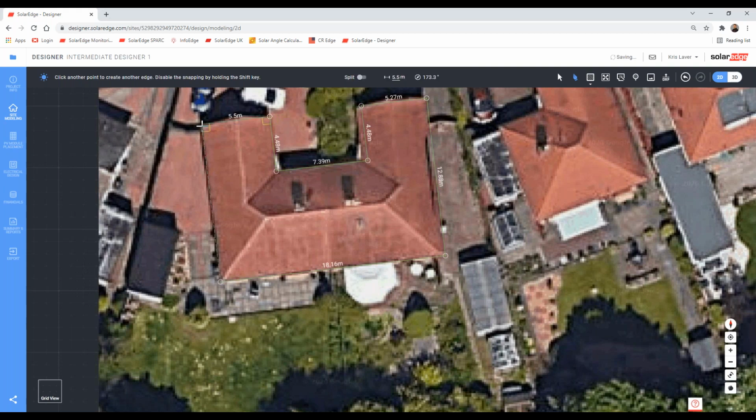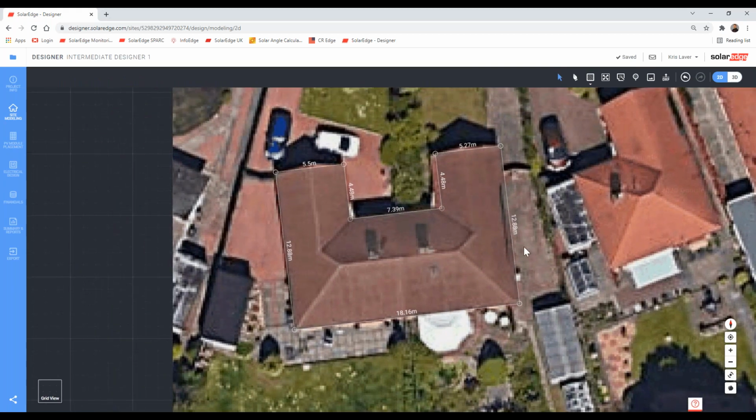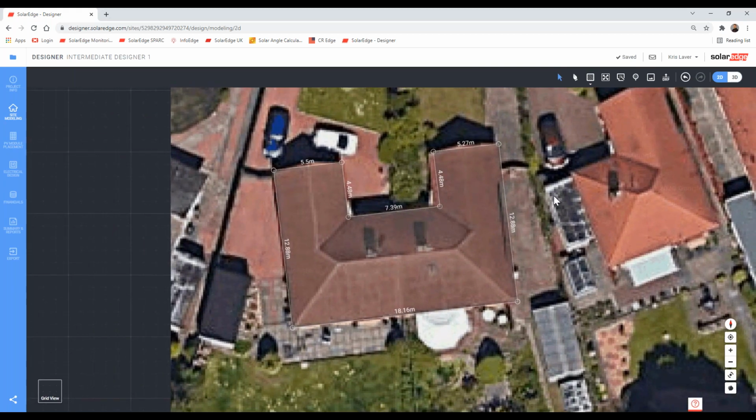Software gave me the indication I was parallel with that line. And as I float this line across, I've got a dotted green line there to show that I'm in line with the first point that I plotted. Okay. What I like to do when I've got an outline of a building, simply click out of the model once with the left click, hold Control on your keyboard and press A, and it will display the angles.